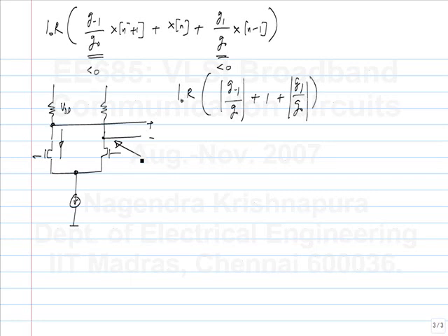See the largest, so let's say this is the output. When do you get the largest output? When this is all the way at VDD and this is all the way at its minimum value. What is the minimum value of this? When this is plus 1, this is minus 1 and this is plus 1. Because the taps are negative, that will add up to the most negative value. Or if you make it the opposite, minus 1, plus 1, minus 1, it will be the other way. And that current has to flow into one of the branches.